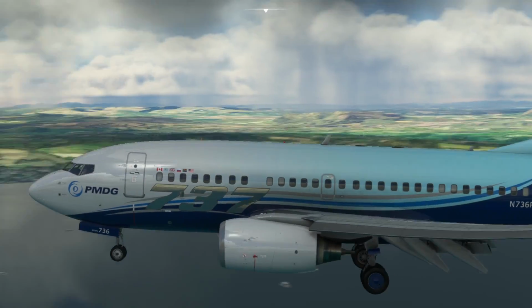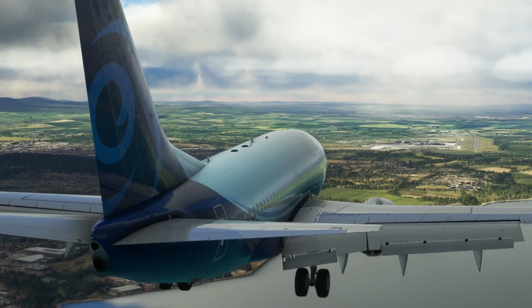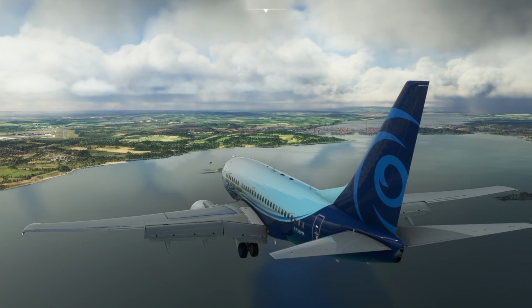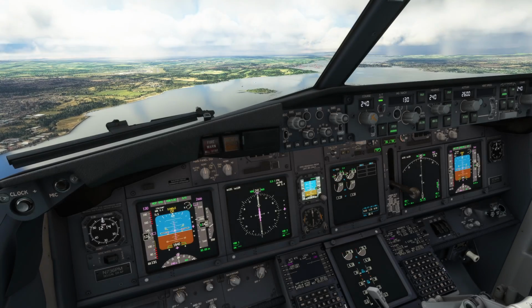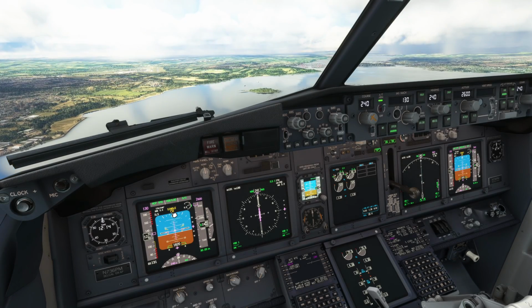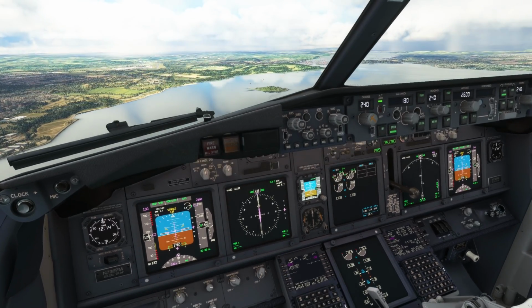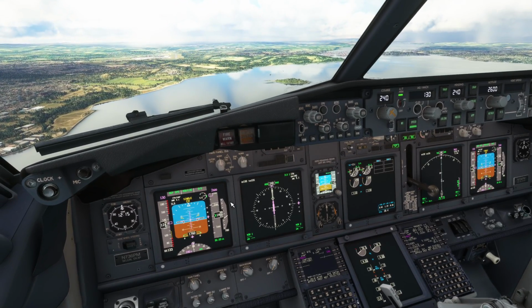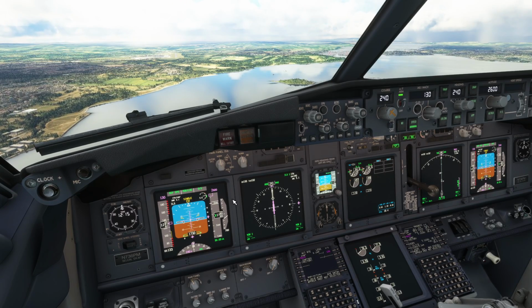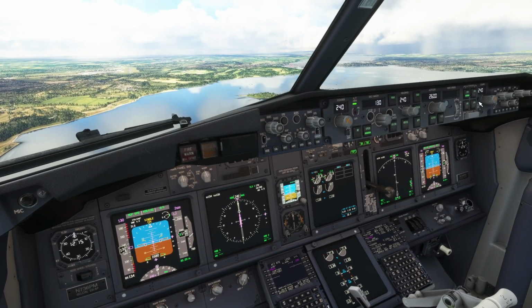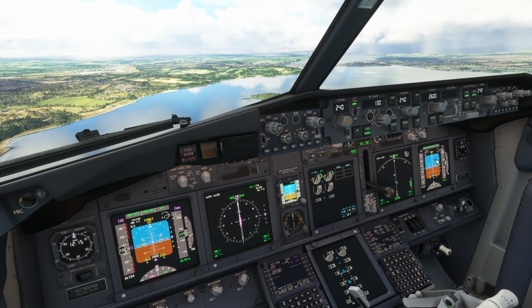Of course, this isn't actual flying, this is programming a computer and watching it. It's very rare that I let an airplane land itself. I'm going to today. Although we've only got single channel on the ILS, so we'll keep an eye on this and see what it says as we get closer. I think on single channel you shouldn't be able to do auto land. That's because we haven't turned both on, of course. So we'll turn both on.